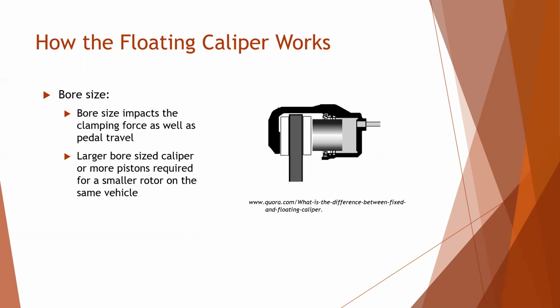Something else to note is that bore size impacts the clamping force as well as pedal travel. If you have a larger bore size inside the caliper, then the clamping force will increase, but because that bore size is larger, there's more fluid displacement needed to get that piston to move than a smaller piston would require.